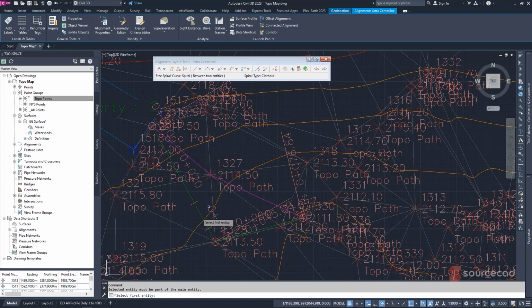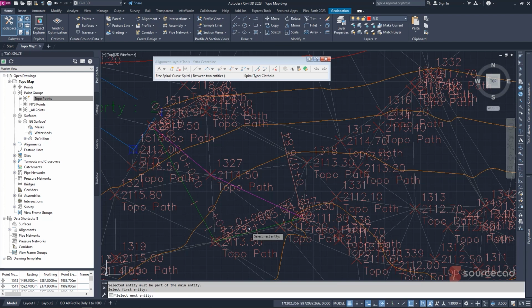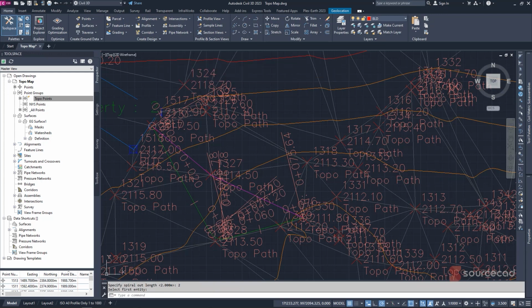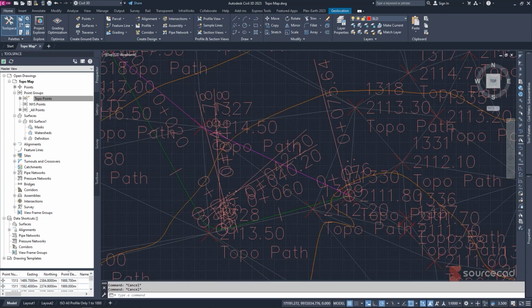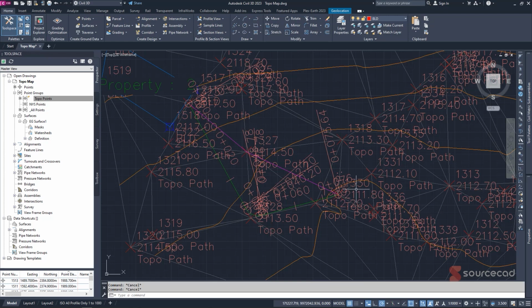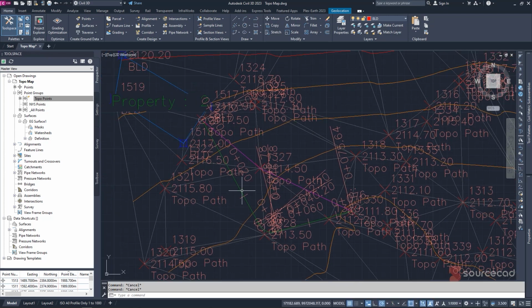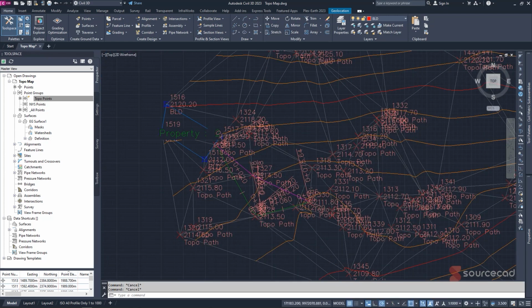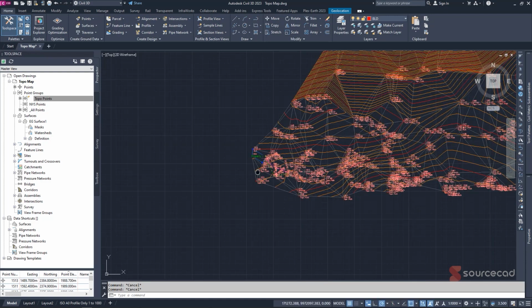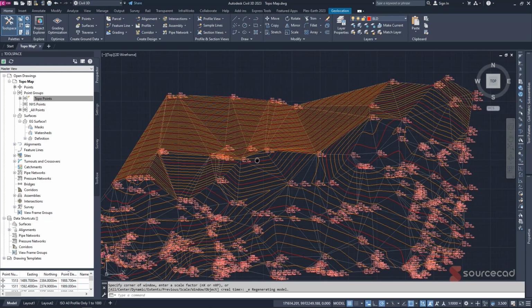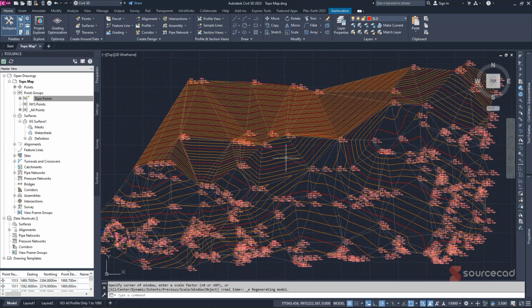And then now we are able to create our curve. This is the first, this is the second, which is less than that. Then we can use 5 meters, then spiral in 2 meters and spiral out 2 meters. We right click to close it. And now you can clearly see that it has given us a solution on how this specific alignment can be connected to this road. So that's basically how we create our alignment and create our topographical maps, showing the information that is required.